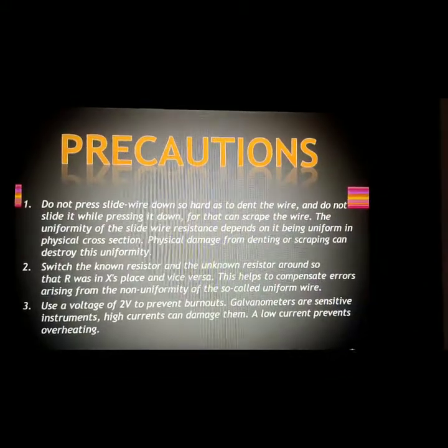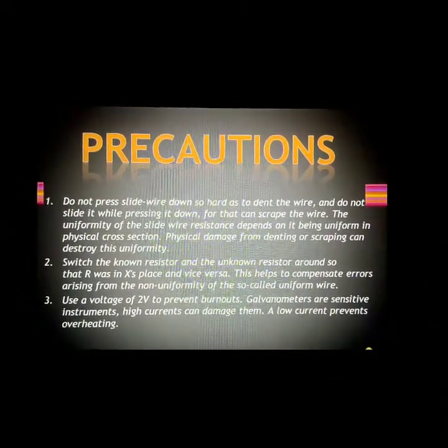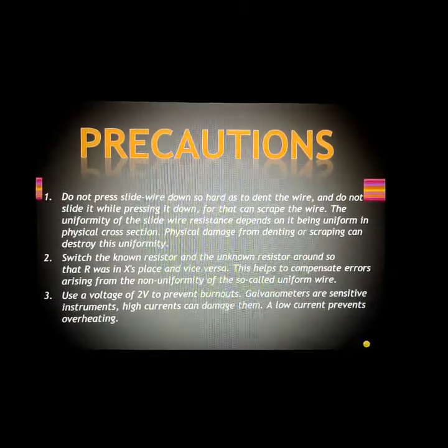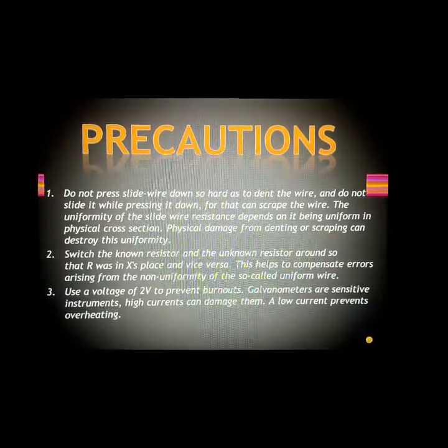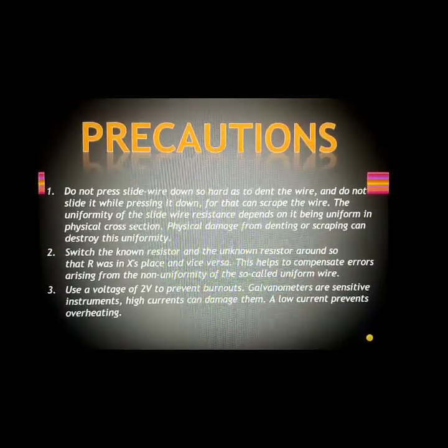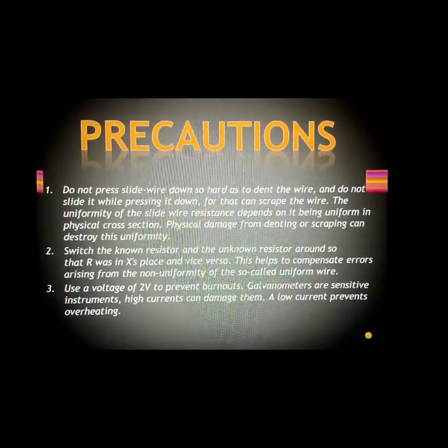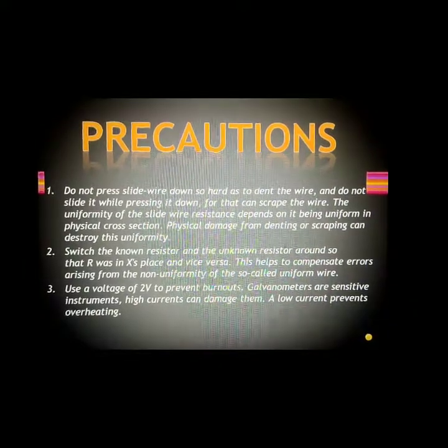Physical damage from denting or scraping can destroy this uniformity. Switch the known resistor and the unknown resistor around so that R was in the other place and vice versa. This helps to compensate errors arising from the non-uniformity of the so-called uniform wire.